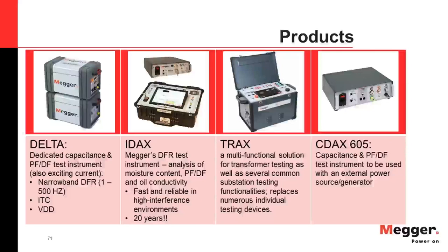And yet in this example, the 3 traces look extremely different, as they should when you're comparing how power factor is changing with frequency, because there are some telltale attributes you're looking for on these DFR traces to make a determination about the source of the not great power factor results. But they all converge to a single point at line frequency. And while the power factor in this one example isn't fantastic, somewhere on the order of 0.45%, or close to 0.5%,